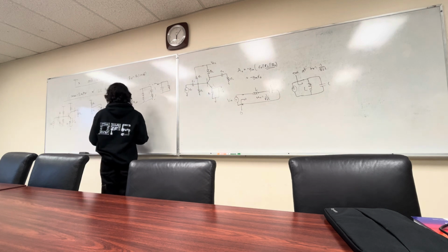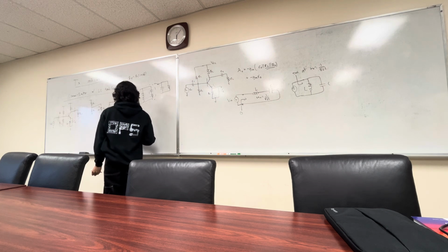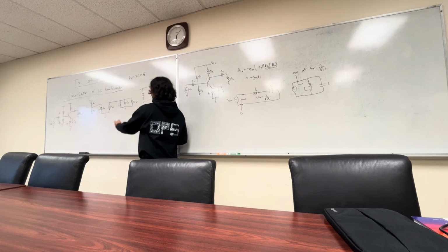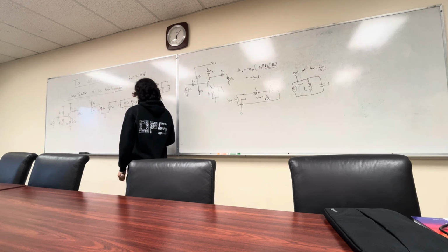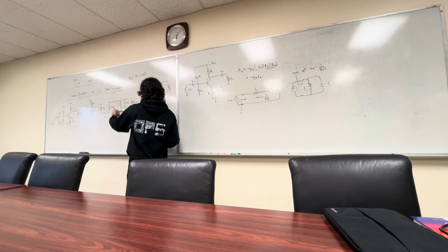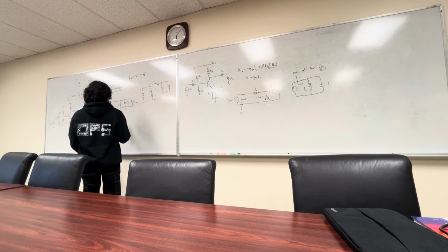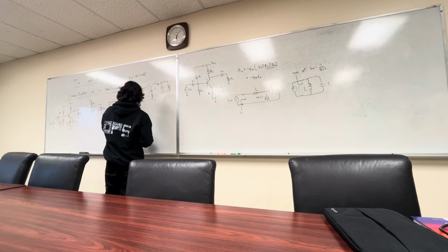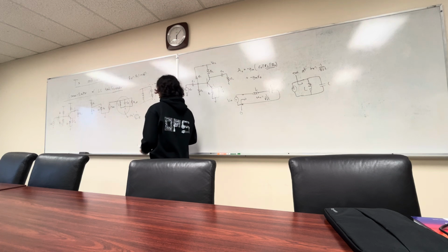Next step is, put that there. This looks like a parallel RLC tank. It's going to resonate at some frequency. We're assuming the BJT has no capacitances here. In reality it does, but it's going to be really insignificant compared to this DC block cap anyway. So next step is, this forms an LC tank. This dictates our resonant frequency from this formula. So now we design this tank to operate at our frequency of interest.